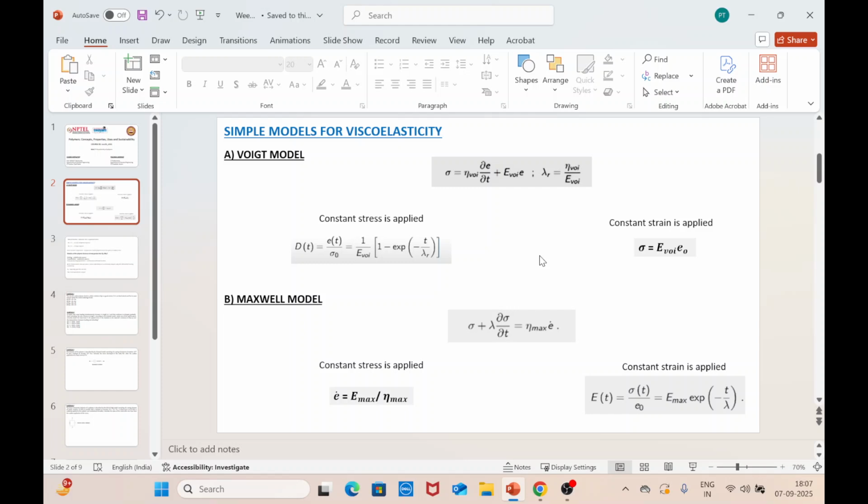But if you see in case of the constant strain, that is your stress relaxation, we see that the stress is almost directly proportional to your strain. Which means that is more like an elastic response or elastic behavior in case of a solid-like material. So that is not exactly predicting the viscoelastic behavior of a polymer, because over there we need to take both under consideration. But since it's a constant strain, this entire factor which is describing the viscous effect is going to be nullified.